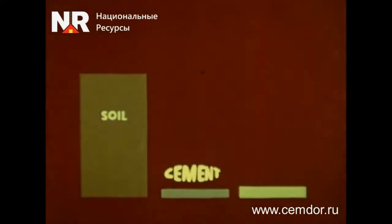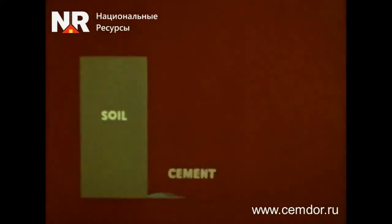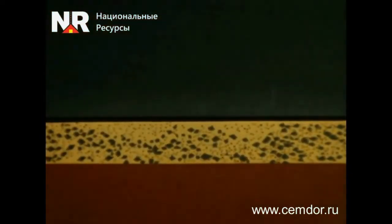Soil concrete consists of soil making up at least 95% of the total mass and Portland cement. The amount of Portland cement depends on the design characteristics of the road section and the stabilizing additive used. Water is necessary for the hydration of the cement in the mixture, as well as to achieve maximum compaction of the soil. When mixed, the soil, cement and water form a dense paste-like mixture ready for laying the structural layer and its compaction. After that, the resulting mixture hardens, gains strength and does not come out of the mold, and it turns into soil concrete, which is resistant to moisture.